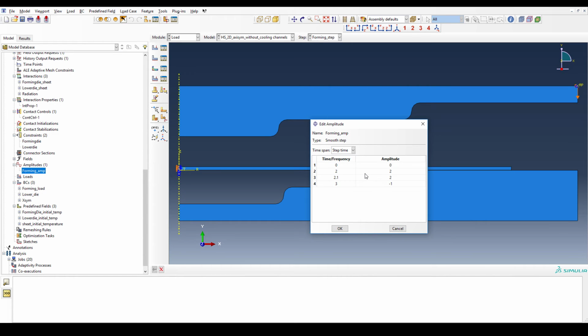So you stay in contact for 0.1 seconds. Why have I given this? As we know, the main idea of hot stamping is that my microstructure should end up martensitic. That's the reason for my cooling curve; there will be a critical cooling curve, which we'll discuss later in the results file.